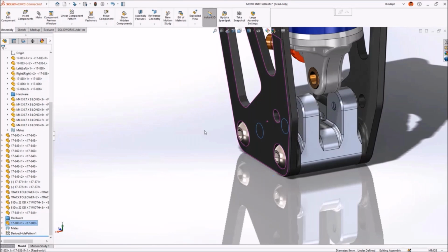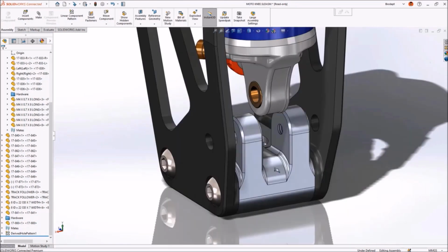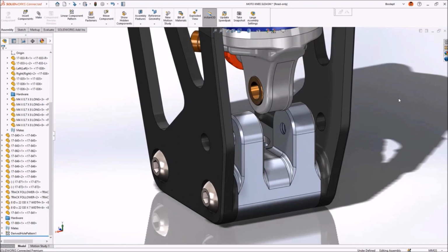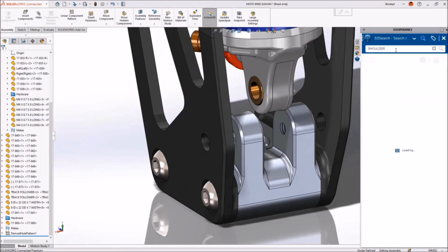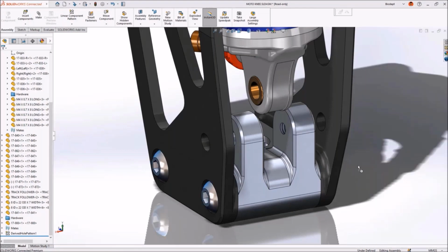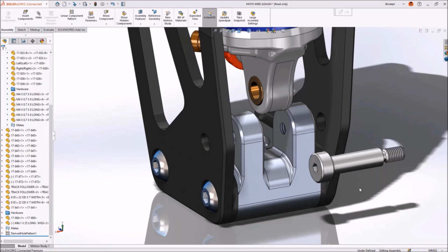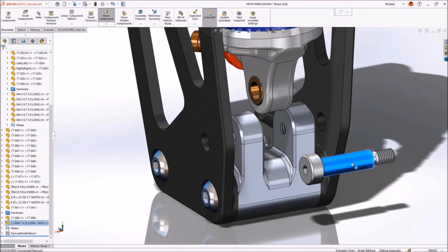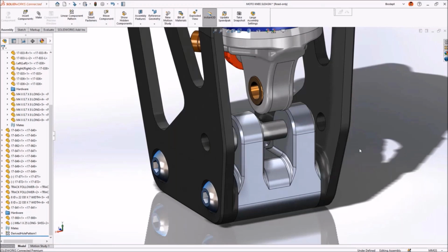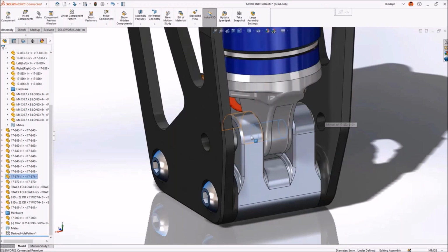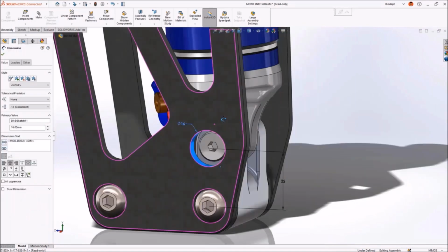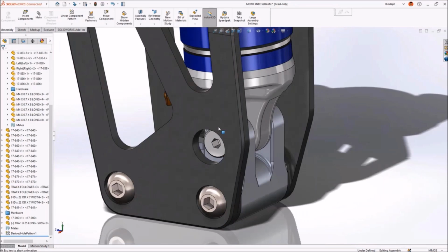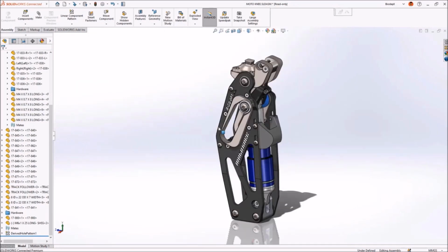Now here we need to again insert a shoulder pin of M6x25. So let's search for it. Again, leveraging the search options, or the functionality of the 3D Experience platform within SolidWorks. So here you can see we are integrating SolidWorks with the platform capabilities. Again, placing this pin by using SmartMate features. The shock absorber assembly can also be positioned by the same method. This hole needed to be changed to 16 mm for the maintenance purpose of that pin. So let's check the motion of this assembly.